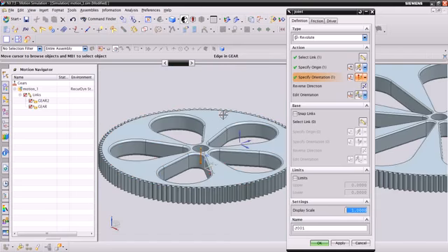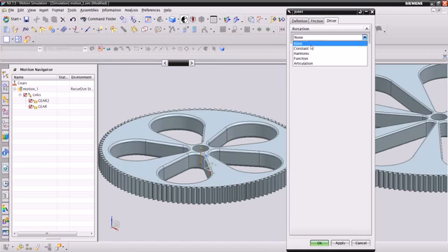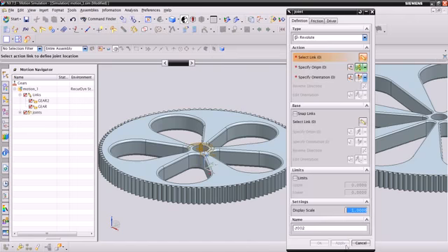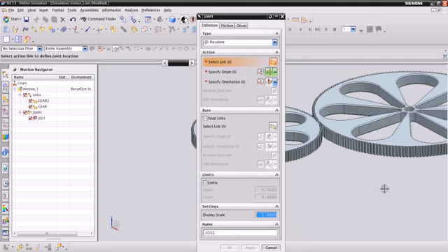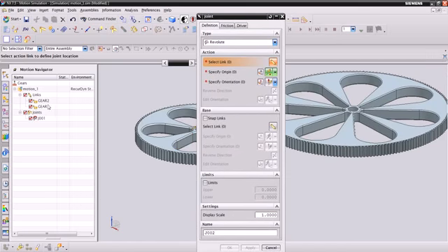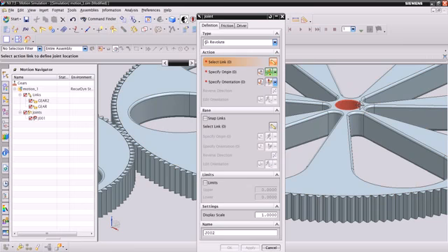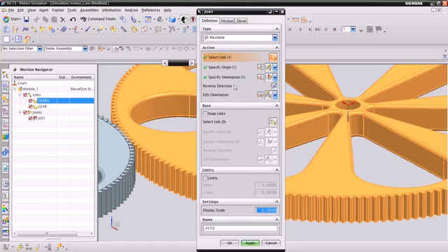We're going to want these gears to move, so click on the driver tab and change rotation from none to constant. Give the system an initial velocity of, say, 50 inches per second and click apply. With one revolute joint defined, we can now define the second. Again, using smart clicking, select the interior edge and NX will automatically specify the origin and orientation.